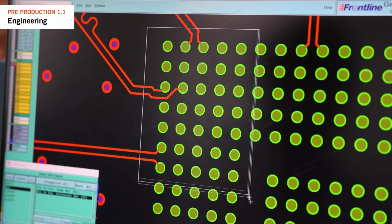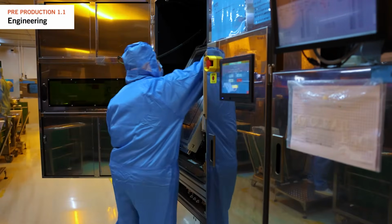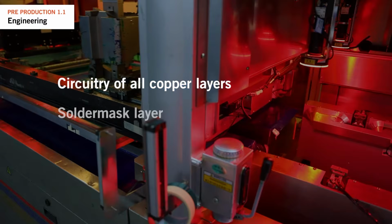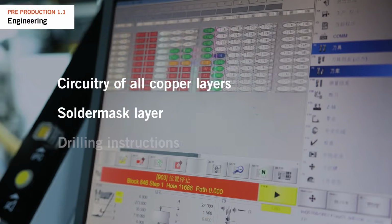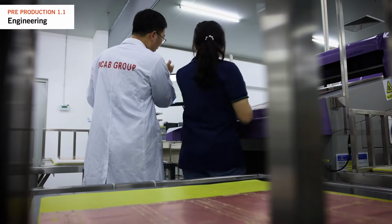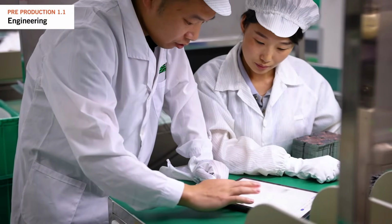Then we take the customer's original Gerber files and generate the working Gerber files. These files are used in the production process to define the circuitry of all copper layers, the Soldermask layer with clearance for pads, and programs that outline the correct drilling locations and drill sizes. We have our own PCB specification to guide us on features that might be overlooked in a customer's specification.